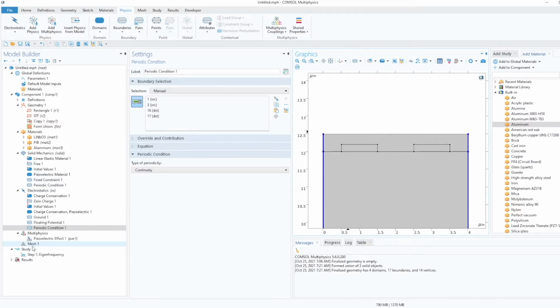So we'll do mesh. Mesh is again a very crucial thing. You should take this very seriously because it may change results a lot. As I rightly discussed in the first video where we discussed the multi-physics and FEM, mesh was the basis of all the analysis. It's the type of mesh you give, and based on that, this FEM tool will approximate your solution.